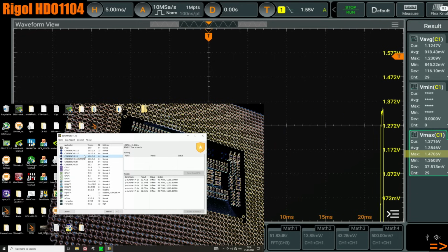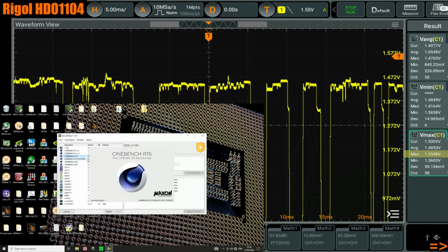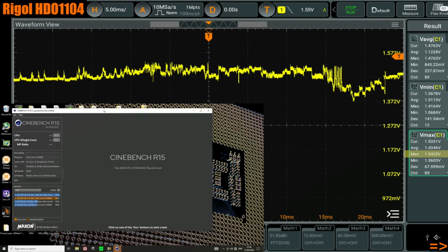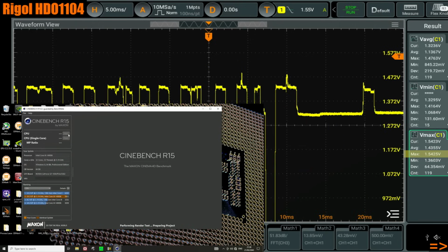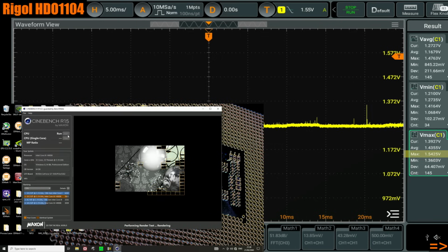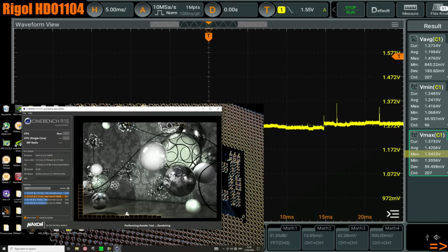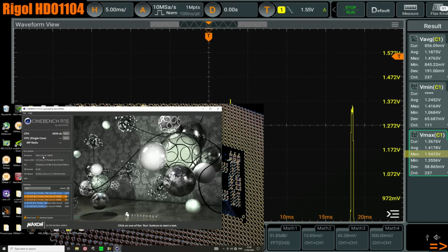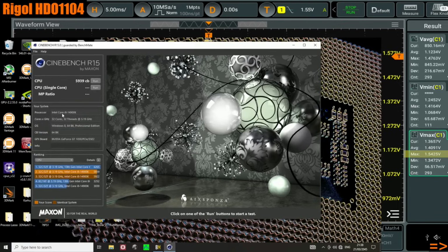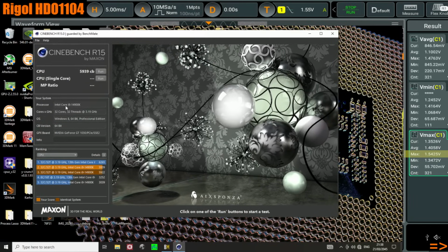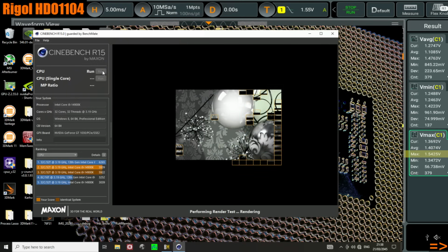I really think MSI has some kind of bug in their voltage controller configuration, because it's not a VID request from the CPU. Now, once you're in Windows, the VID limit does its job, and as you can see, 1.54 volts. The reason I'm running Cinebench 15 is that it just so happens to trigger the highest voltage spikes out of the various applications I've tried.